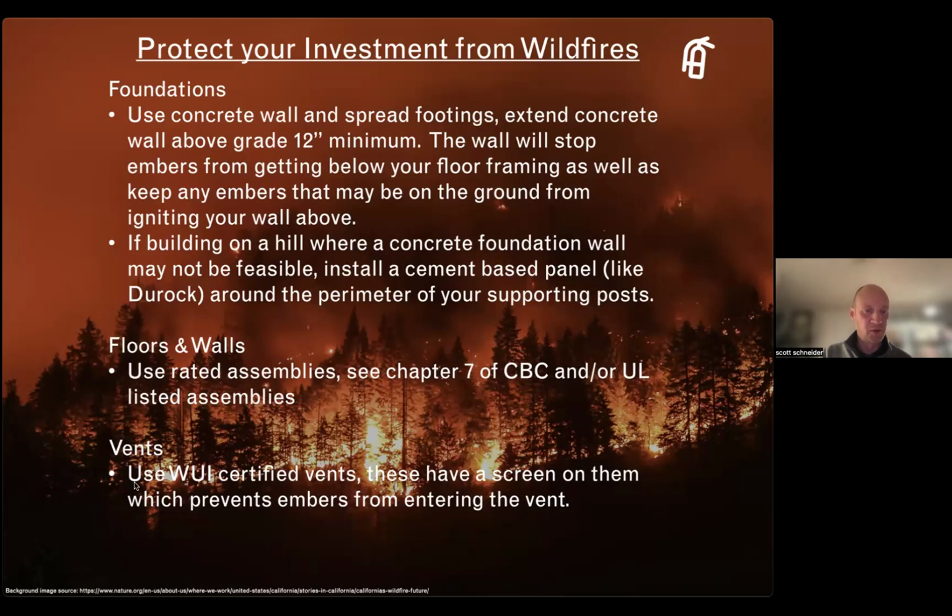Vents, you can use WUI certified vents, and basically what those are is, I think, no larger than 1/8 inch openings in them, so that they vent, but they prevent embers from being able to get into the vent and starting a fire.